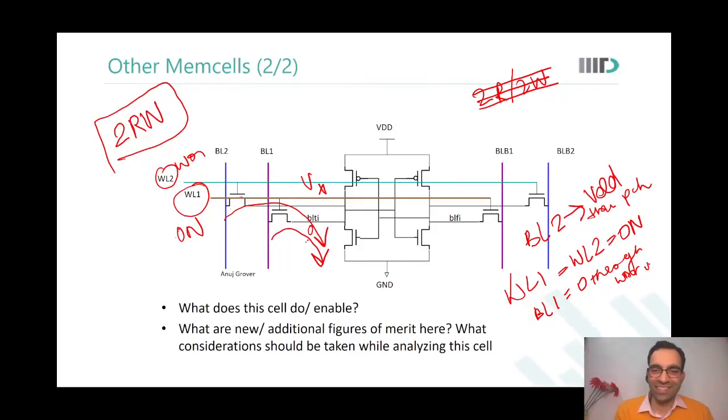And sir, there was also one question. When we were doing the cell optimization, with a small PD the writability would improve. But when I'm talking about the writability, I'm focusing on the zero, how efficiently. So why am I considering PD, that a small PD would improve the writability?